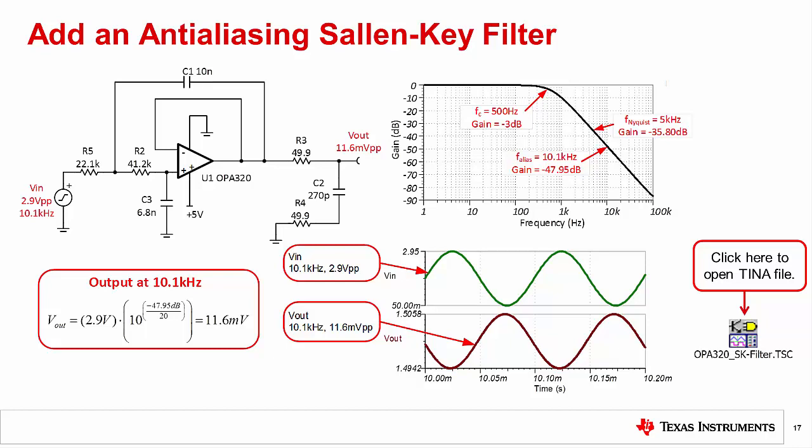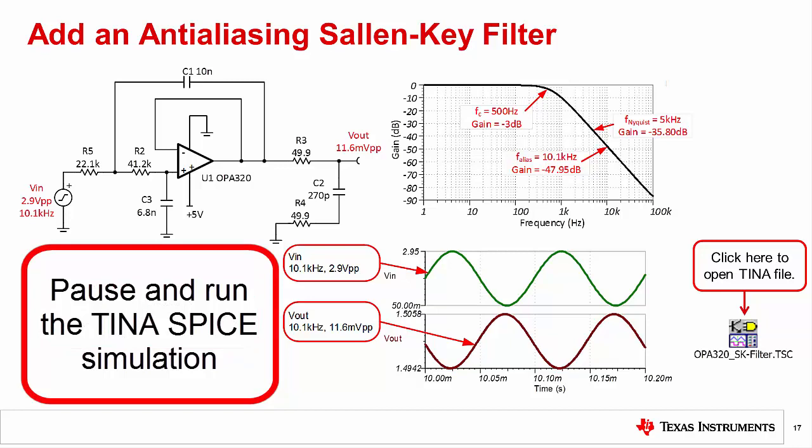You might have noticed that the output signal appears to be inverted even though the circuit is a non-inverting topology. This inversion is actually a phase shift introduced by the second-order filter. Pause and run the TinaSpice simulation.